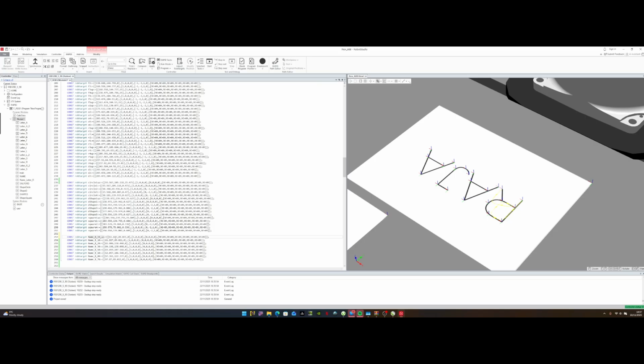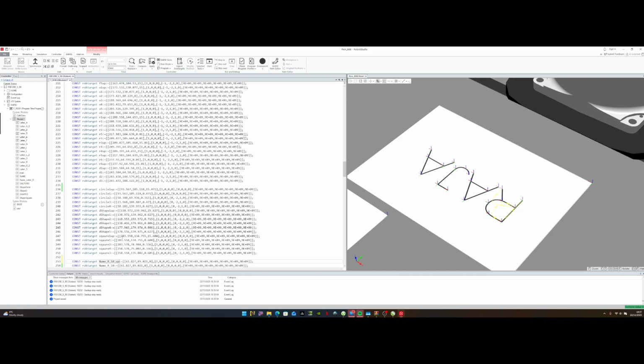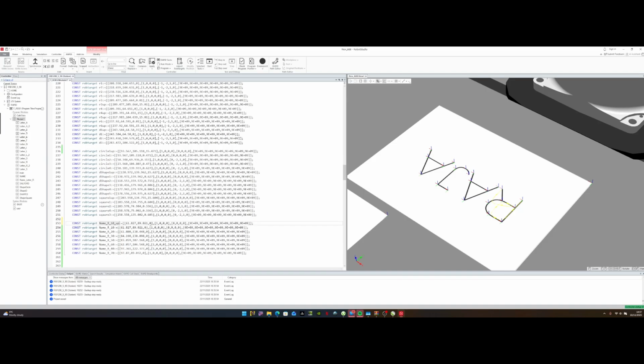But now the target itself, I need to modify the Z position. Okay, so this is X, Y, and Z. The Z position of all of them is 0 because according to the work object, it is flat on the table. This is the X and Y position, and this is the Z position. So for this one, I can modify that Z position to something. Let's say I modify it to 15, because if you notice, all my ops I've been using 15 point something. So I'll modify it to 15 just for that target.